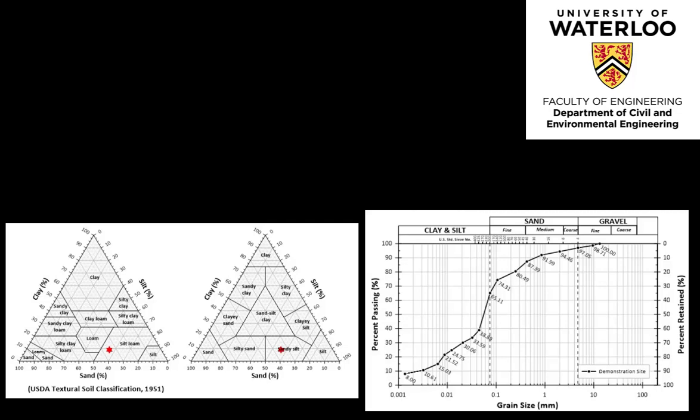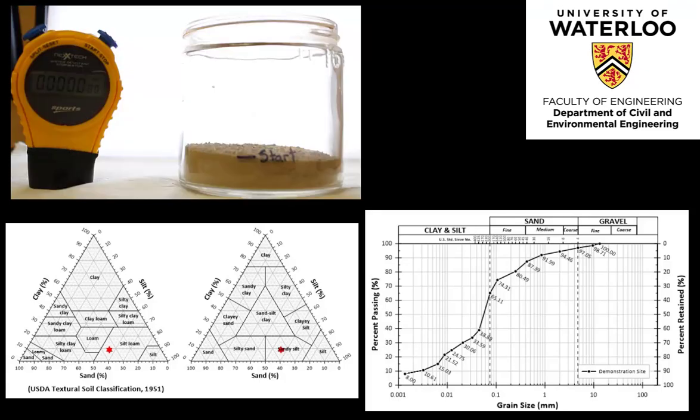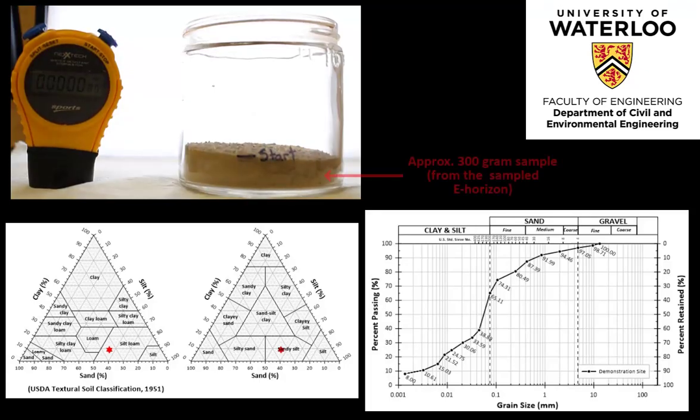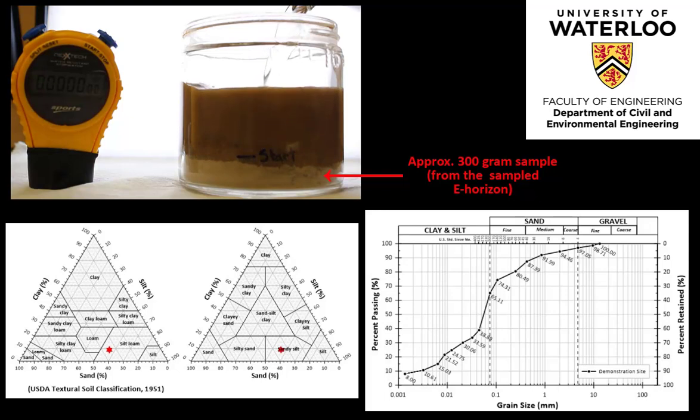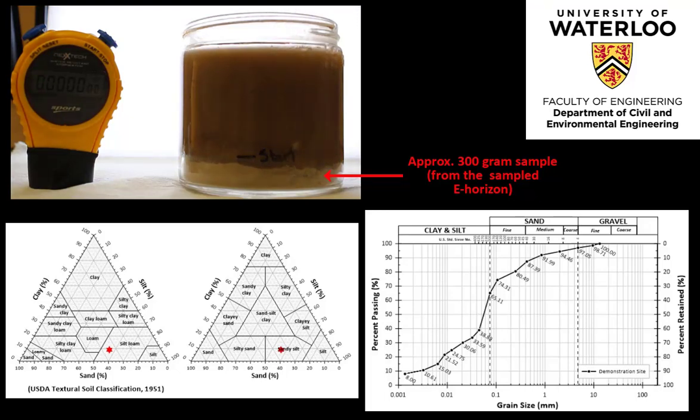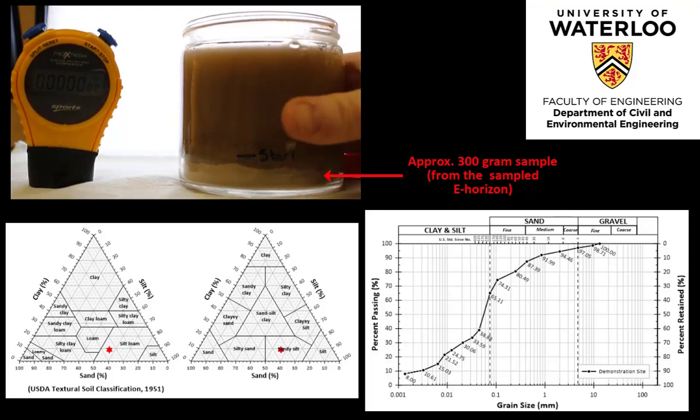One final test will be compared here for classifying soils on the trilinear diagram by employing the jar shake test. Although this is an inadequate test from a geological engineering perspective to classify the grain size distribution of any given geological unit, if properly conducted, the test can provide a reasonable estimate of the general soil classification designation.